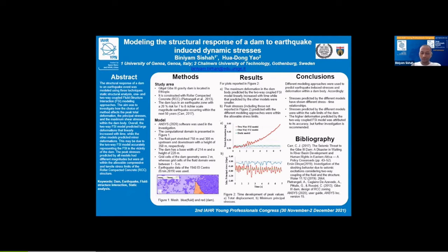The response of a dam to forces of uplift, weight of dam, and hydrostatic pressure can be easily computed using a static model. However, when earthquake-induced hydrodynamic stresses and inertial forces are present, the use of FSI simulations helps gain an accurate understanding of the system.